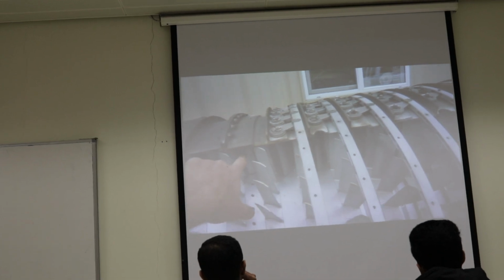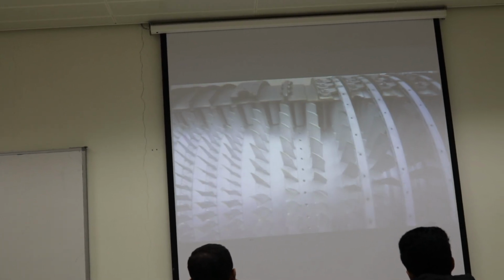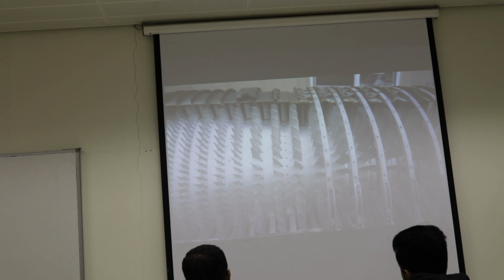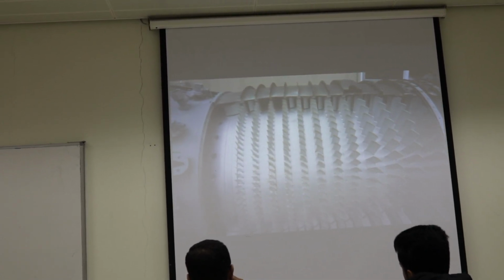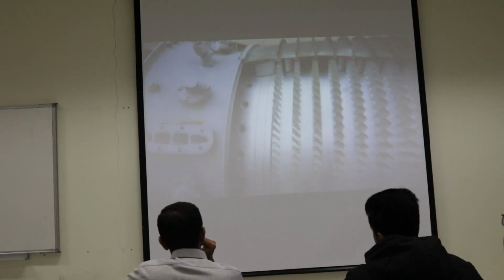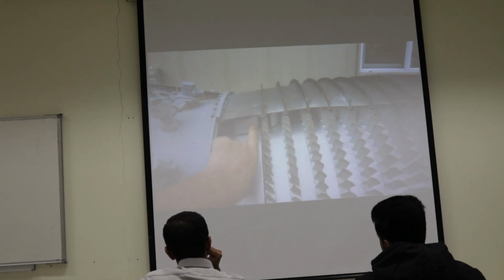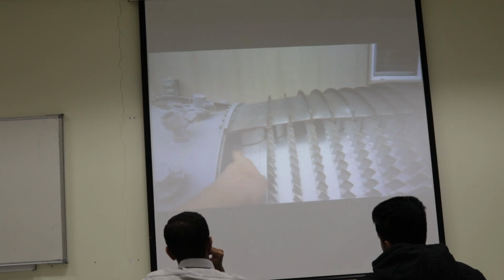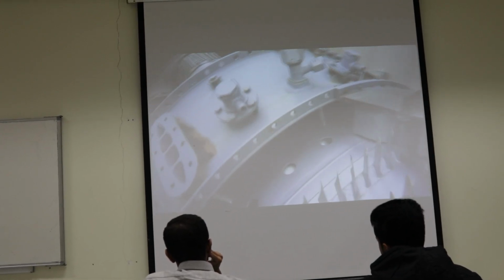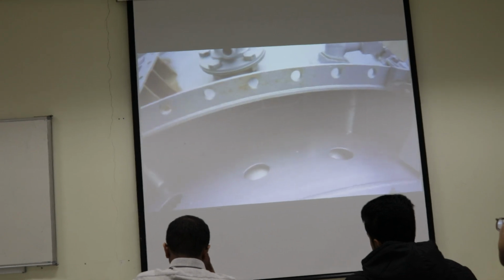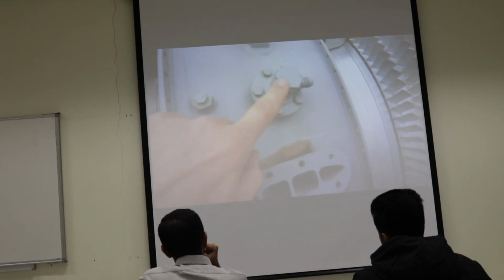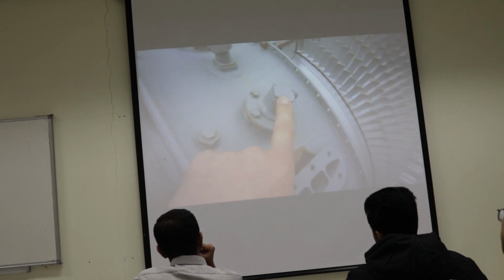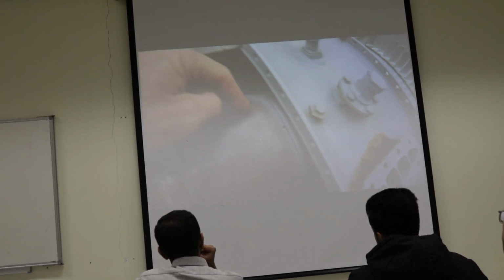The stators are not variable. So the blades of the compressor, guys, are very thin. You can see each stage compresses by about a 1.1 to 1 ratio, and the size decreases as it goes. The outlet guide vanes direct the air straight into the diffuser, the mid-frame diffuser, which contains the fuel nozzles. These are liquid fuel nozzles. They inject fuel directly into the combustor cans.